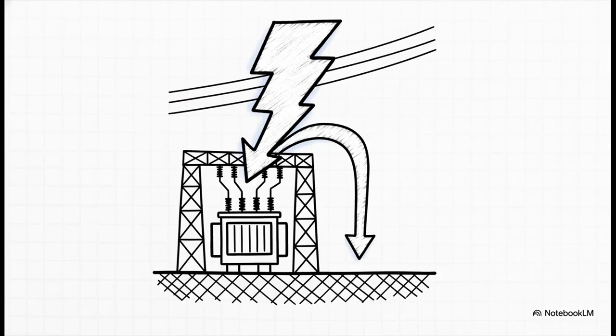But, it's crucial to remember that during a fault, not every single amp of that massive current shoots straight into the earth under our feet. That's where the current division factor, Sf, comes in. It's the ratio of symmetrical grid current to total ground fault current. A large portion of that current is actually safely returning to the source via overhead ground wires and neutrals. Factoring this in is huge because it prevents us from wildly overdesigning our systems and wasting a ton of money.